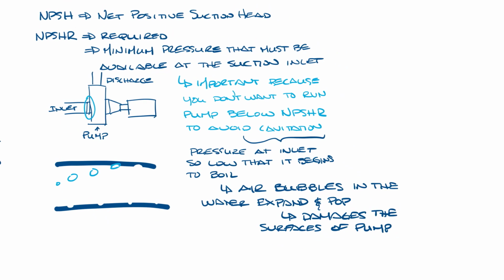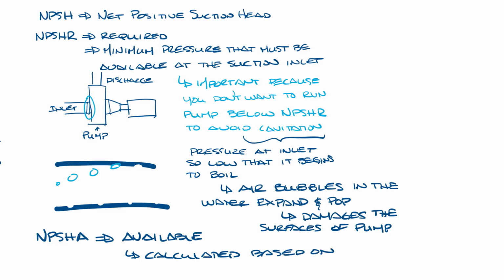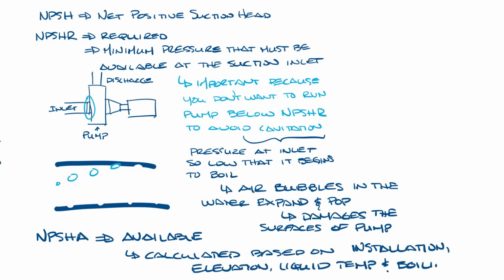Let me make a little more room to talk about NPSHA. This is the available NPSH. This is calculated based on things like installation, elevation, liquid temperature, and boiling point. You want to make sure that the NPSHA is greater than the NPSHR. Okay, let's scoot this over.